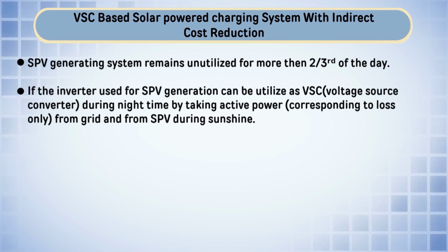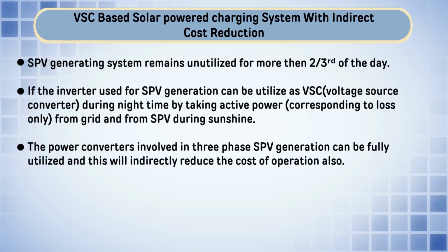Another topology, we may have wind energy based charging stations, and in the case of a wind energy based charging station, we have integrated solar energy and wind energy at the DC bus, and two vehicles which require fast charging are integrated at the DC bus, and a centralized converter is utilized here as a DC to AC or AC to DC conversion unit.